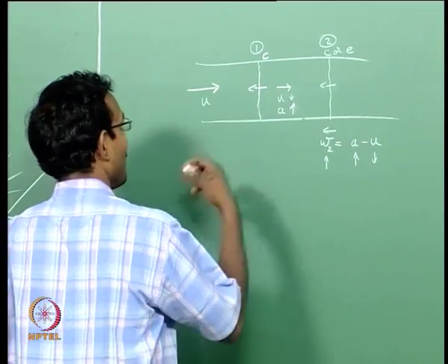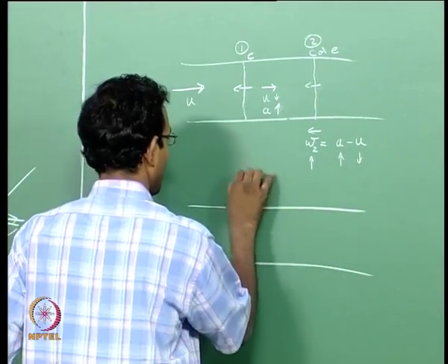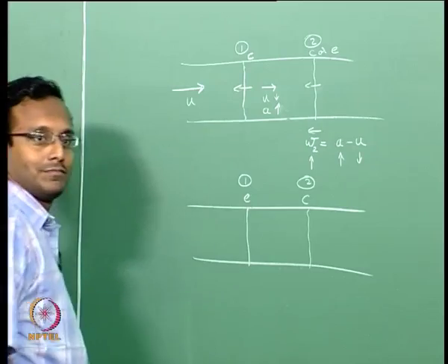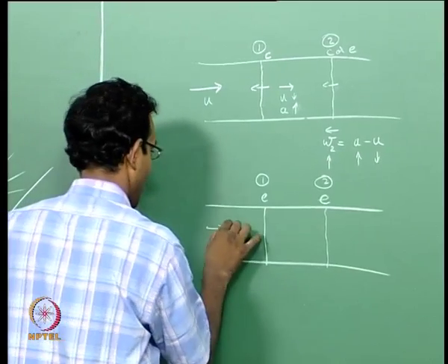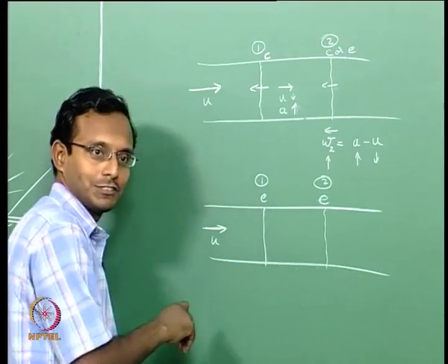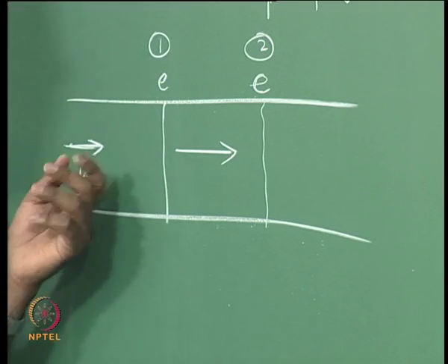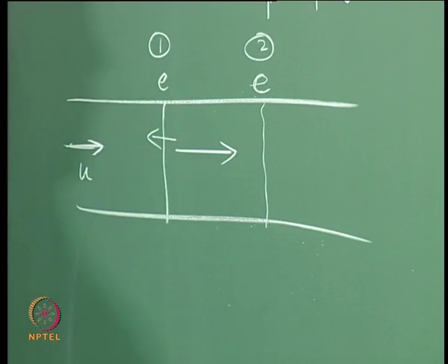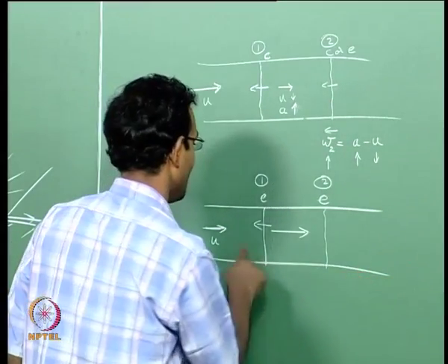Okay. But if the first wave is an expansion wave, I will pick another case. This is my first wave and it is an expansion wave, and the second wave, let us think, is the expansion wave, first thing, easiest. Okay. I have a flow and initially my velocity was this much, after that velocity will be higher. Why? Expansion wave will induce a velocity in the opposite direction. It is telling there is more space there, go there. Okay. That is the information told by this first wave. Wave is going this way, it is telling everybody to go the opposite direction. That is what is happening here.